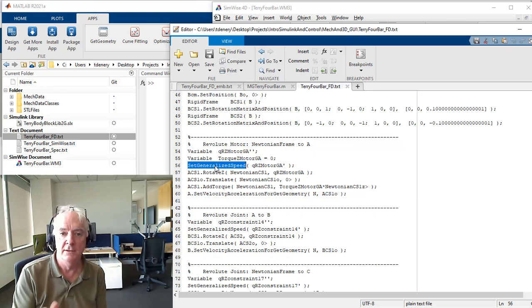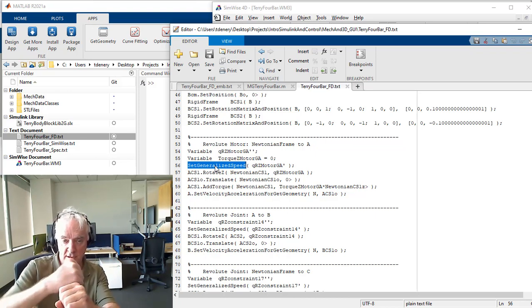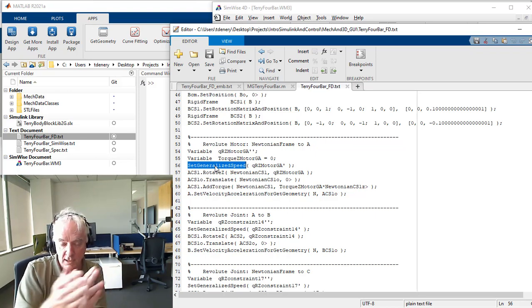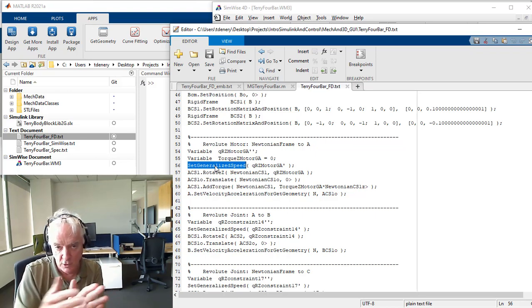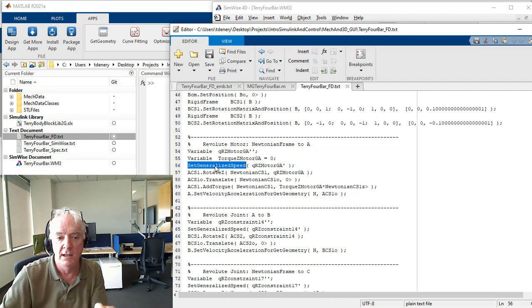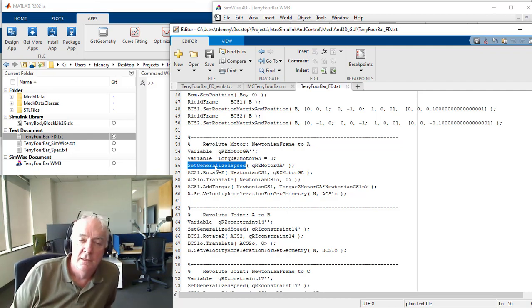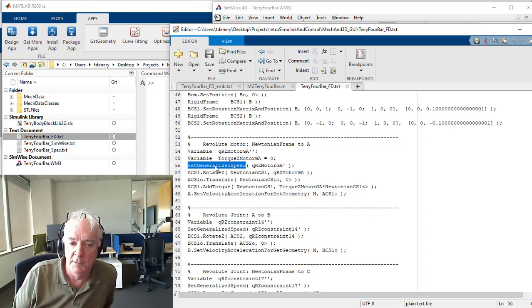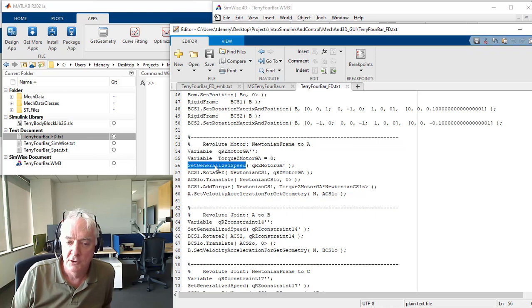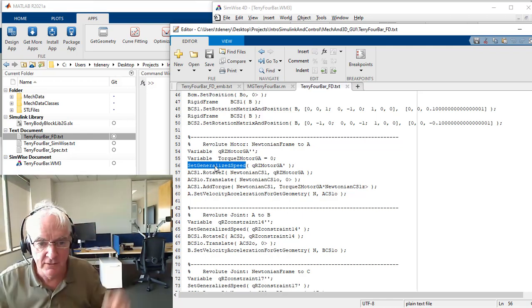If it's a revolute joint, the coordinate is an angle; if it's something that extends, the coordinate is a distance. He realized that the equations can be formulated in terms of the speeds for each of those degrees of freedom, and that introduces terrific efficiency in the expression of the dynamic system.